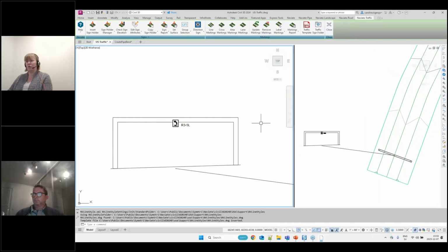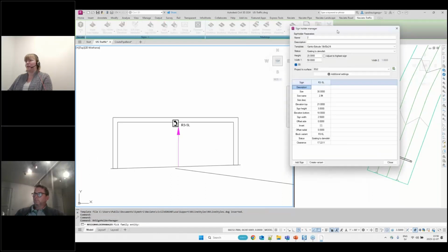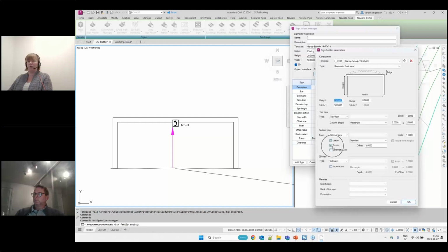In this case, I have a portal that I have here, and you'll see this line over here. You can see that the legs are different elevation. So if I go into my manager, and I'm going to edit this one, and I'm going to say that this one should be to a different surface, we'll see that the surface actually moves and the legs move as well. So this actually shows how the surface moves. It's a setting, you don't have to have it, but it's a setting inside here if we want to have a terrain or not. So it's just easy to see.